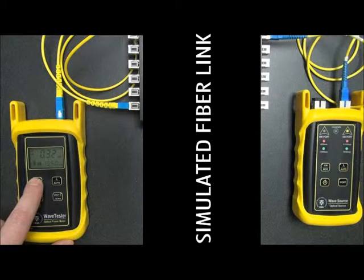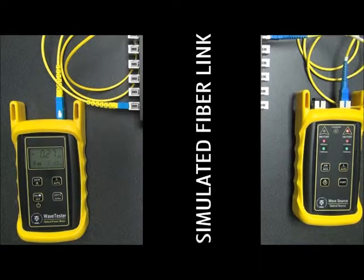And finally, we store readings for port number 6 here. Now, as you can see, it said 12 there, which means that we stored 6 fibers with 2 wavelengths each.